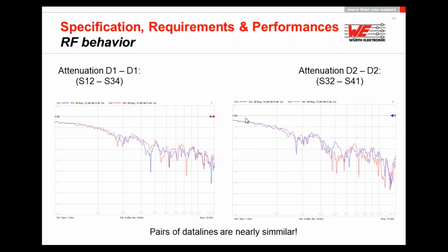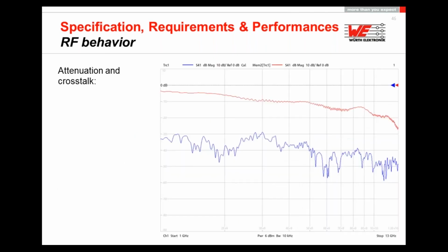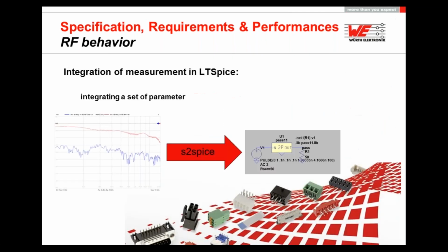And there's one point on the side of that seminar. There's an S2 Spice tool existing, and that helps you as a designer to implement the real measured curves into your LTspice model. But there's one point we have to keep in mind. First, you have to download the S2 Spice converter. Here's the link in the presentation. And these S parameters have to be in the Touchstone format, otherwise you will not be able to transfer that into your LTspice model.